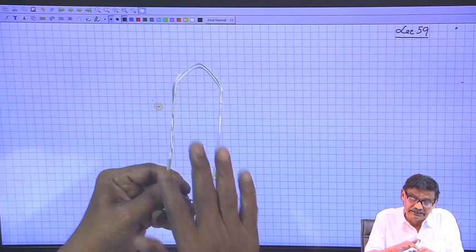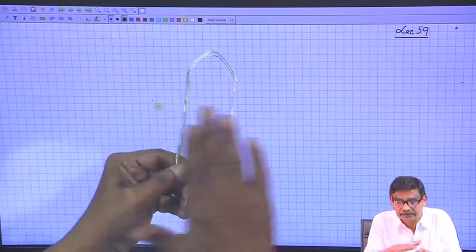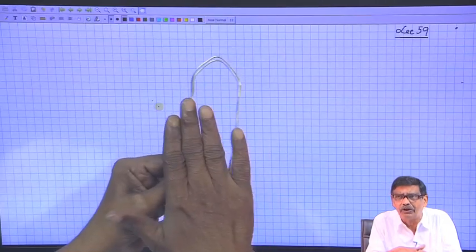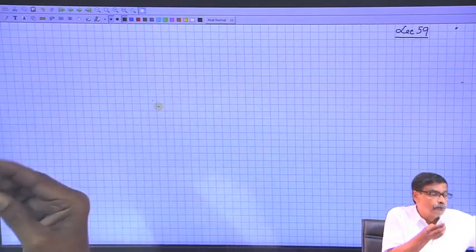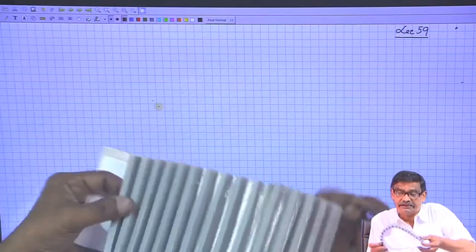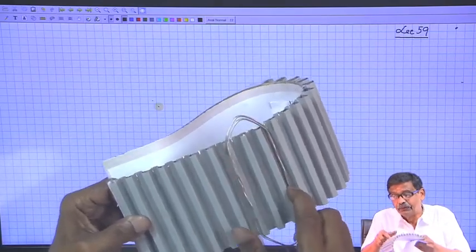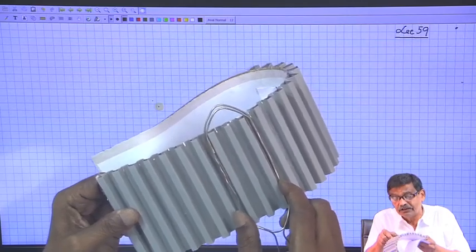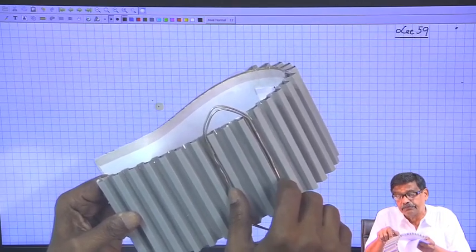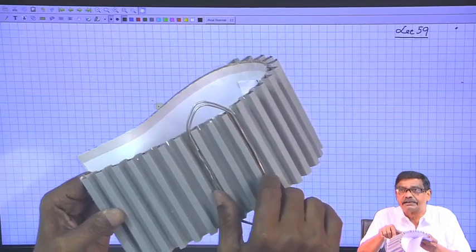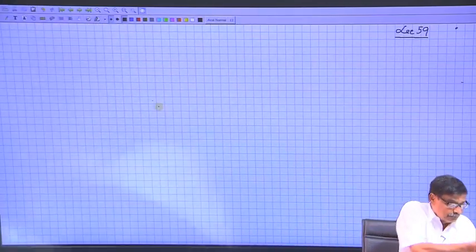So, this is the coil side and its return will be a little lower. These 2 coil sides will not be in the same plane. Then only if you place one coil here like this, its return will be in the lower deck of this slot and the starting coil side of this coil will be in the upper deck. Got the point hopefully. Let us proceed.